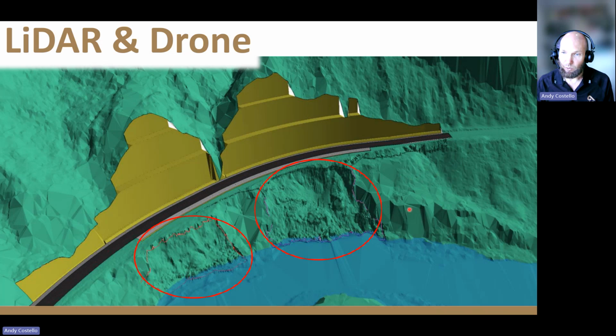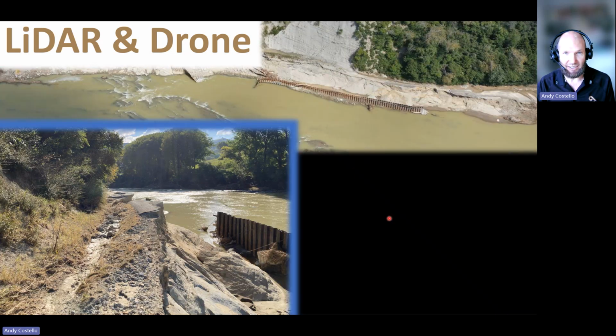You can see we've got the smoother LiDAR data here, and circled in red is where we've brought in the drone data. Merge them together, and then you've got a terrain where you can start building a road and say with confidence that yes, it can be done, but you're going to have really big steep cut batters, and you're looking at 50,000 cubes. So they were really stoked with how quickly we were able to turn around this sort of thing and help them optioneer, I think is the term they use, trying to figure out what to do with some of the storm damaged infrastructure.